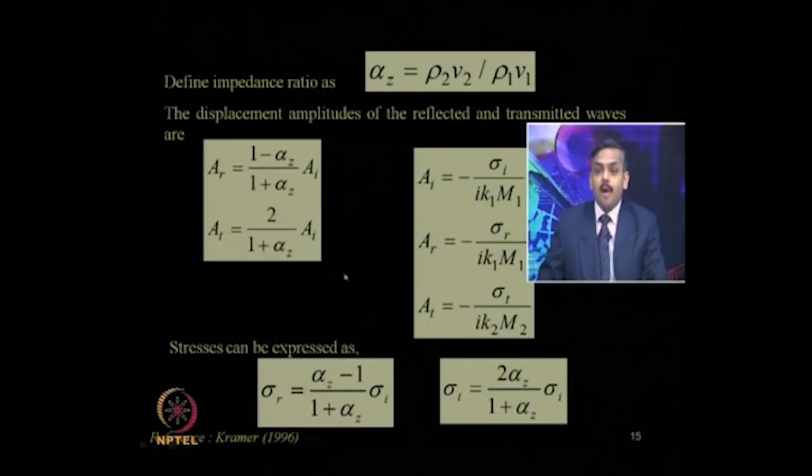So, basically from the base rock level or bedrock level, where that earthquake focus exists, that wave will start traveling in the form of seismic waves. Now, when this wave travels and finally comes close to the ground surface, after traveling through various layers of material, that is from rock to stiff soil to soft soil typically, we should know what will be the changes in the displacement amplitude and stress amplitude, because that is most important.